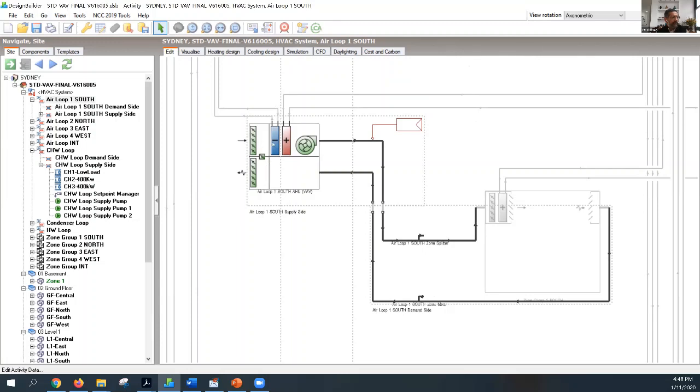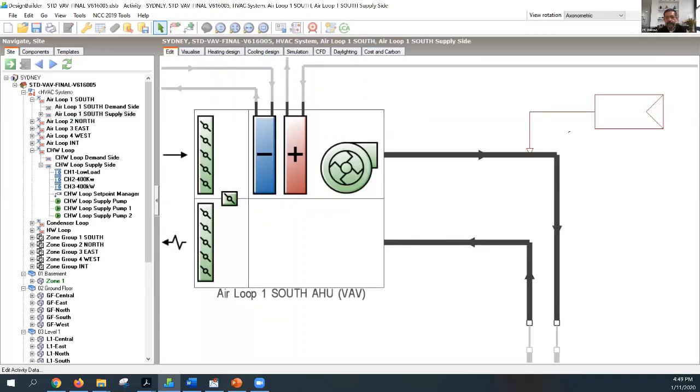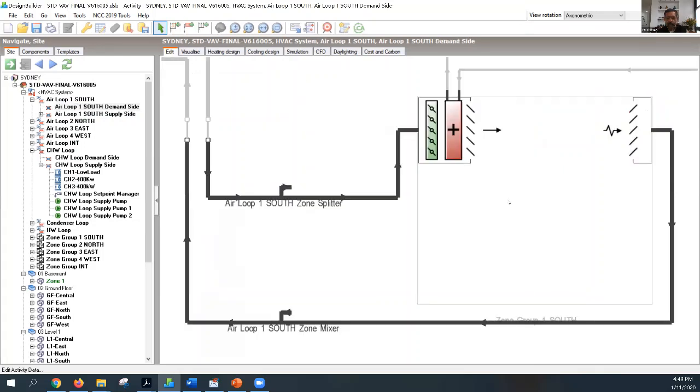The air handling unit's got a cooling coil for chilled water, a heating coil, which comes from the boiler, which is probably unusual in India, but we have them here. There's a fan that blows air through the ductwork, and it comes to the zone. Okay. So again, the same sort of thing applies. You have a supply side, which is really your air handler. This is supplying either cold air or warm air to what is demanding that cold or warm air, which is the zones.